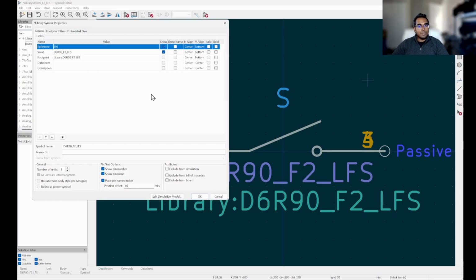Remember, the reference designator is the symbol or the very short text value that shows up on your schematic and on your actual silk screen on your PCB to indicate what part goes where. So we want this to be something that's easily readable and something that we'll recognize as soon as we glance at it. So if I see SW, I'll immediately recognize this as a switch. And KiCad will, every time we place one of these switches in our actual schematic, add a number after it. So the first switch that we place will be SW1, and then the second switch we place will be SW2 if we were to use multiple.